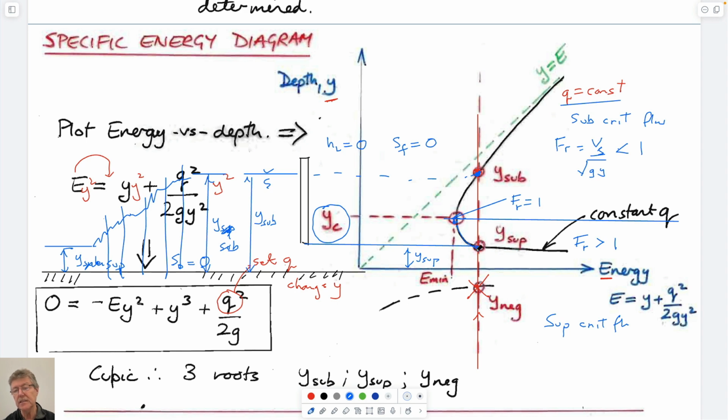Here it's done it spontaneously because I presume that it's right on the edge of here. There's something that's pushed it through here. And we could imagine that the thing that's done this is some bump that's managed to push it along this portion here. It's changed the depth of flow by changing the critical depth.